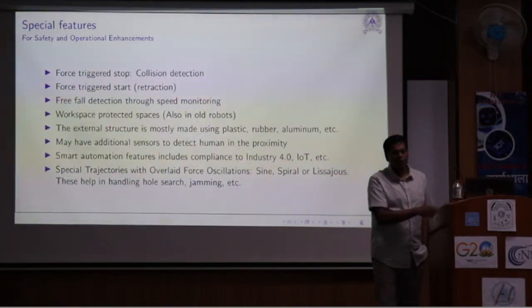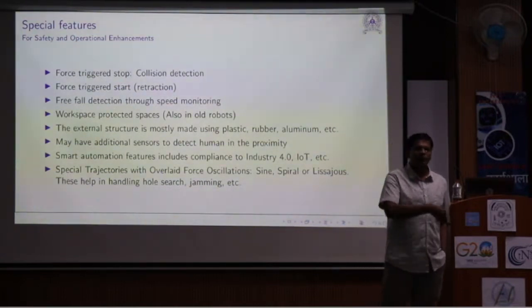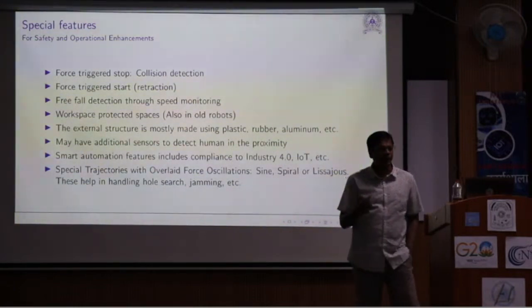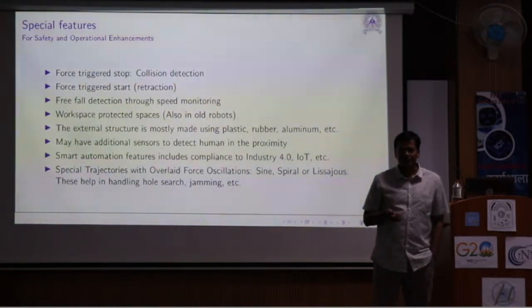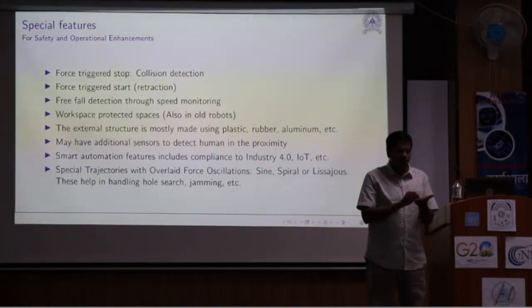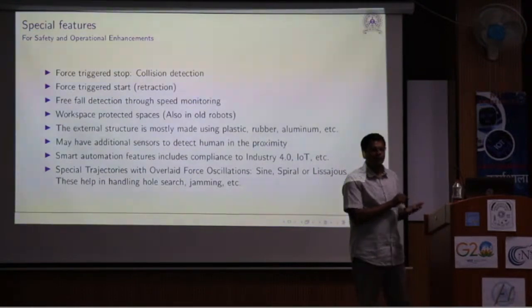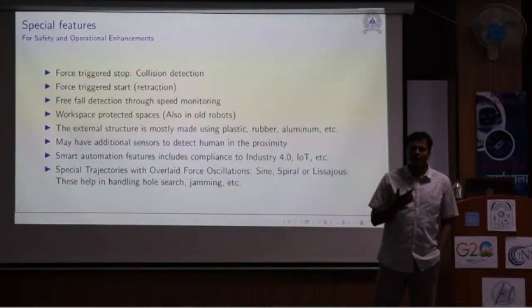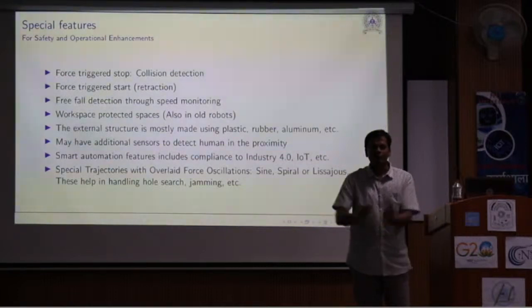In any operation like gluing, welding, painting, it is not only position that is important, it is also trajectory, and time. Why? Common sense. Time is very important. If you are not just supposed to move from point to point, you are very specific about the velocity with which it is moving along the surface. Why? Because let's say you are doing a welding operation, if you stop anywhere and keep welding, what will happen? A huge lump will be deposited there.